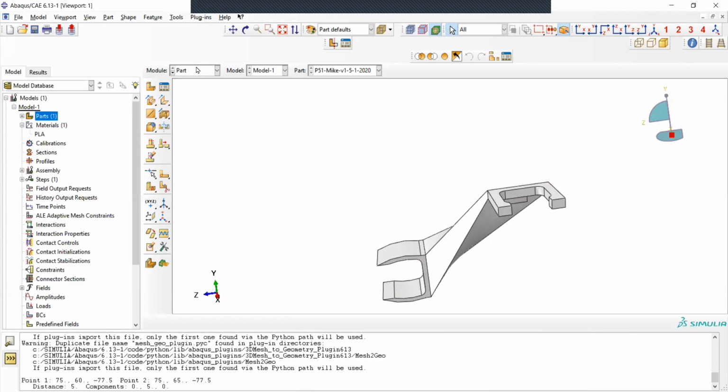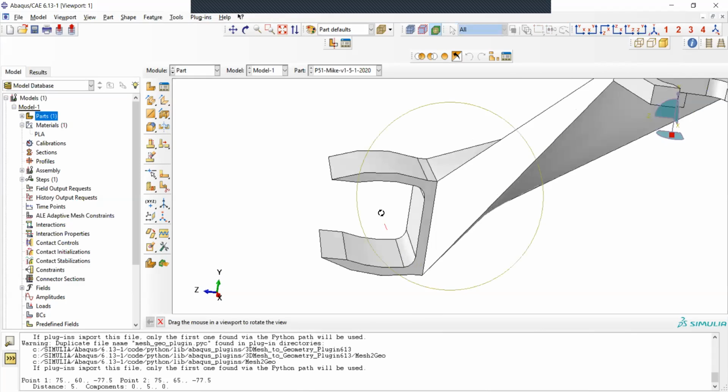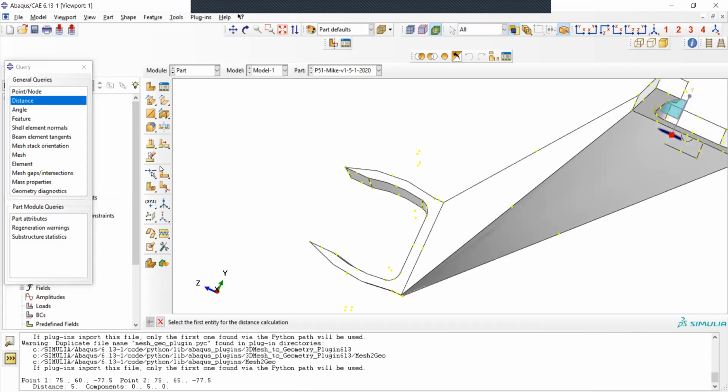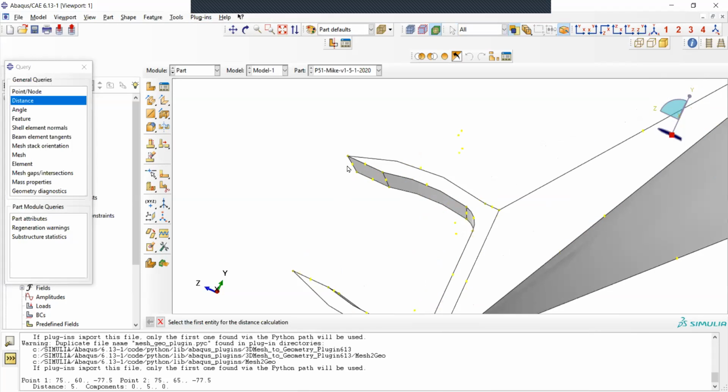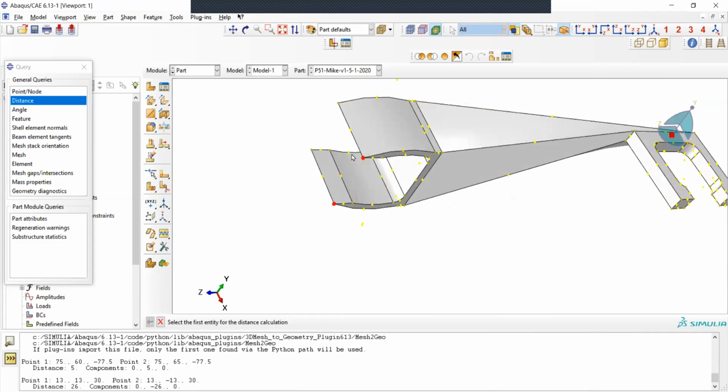And we have no other parts at the moment, but we need the table at least. So we still need to create the table. That is very easy, very quick. Before I do that, I'm gonna measure the opening, and I don't want the table to have any gap between this U shape and the table. It's better to have no gap. So I'll draw my table to be exactly the same width here. And that's 26 millimeters. So my table has to be 26.